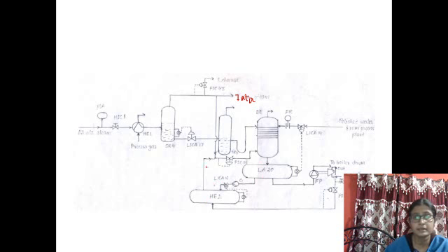We need to consider which is the more important process variable, number one, and the controller is mostly PI type, except if there exists any slow process, that is, if there exists any temperature control system, then only the derivative effect is needed. Otherwise PI control is sufficient for all.